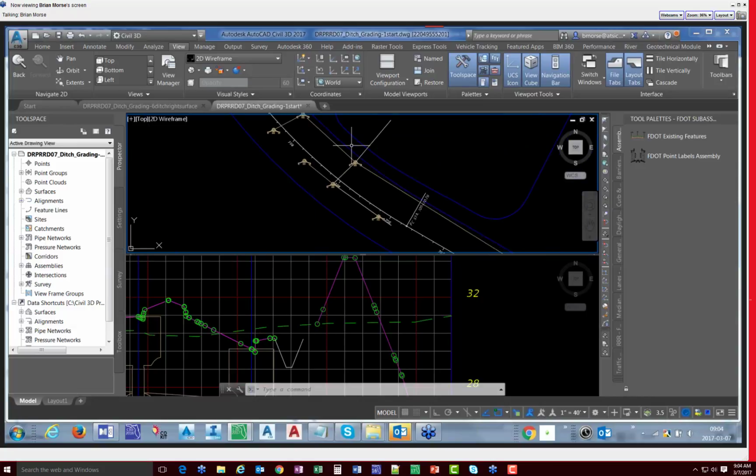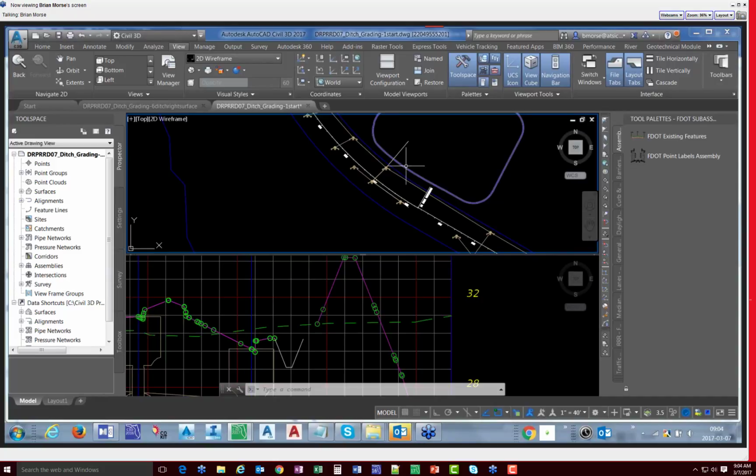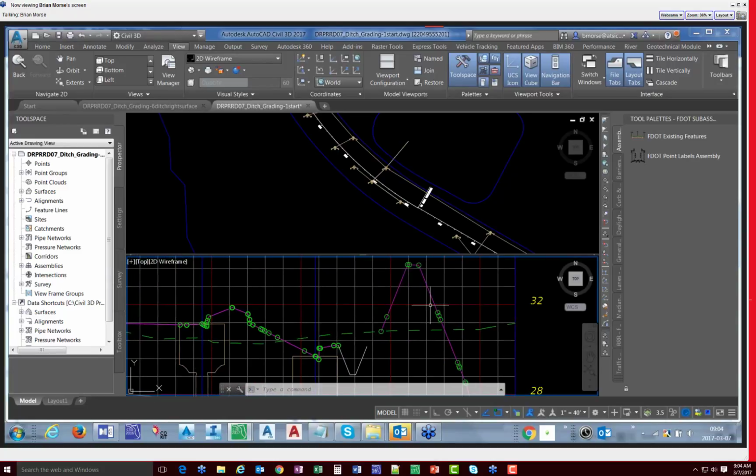What we're going to do is try to fit a drainage ditch right in between the pond and the road, because the berm coming off of the pond pushes the water right into the street, so there's no grading. You can take a look at the profile that we have here. There's the berm for the pond, and this is the back of curb, and then here's our drainage structure. This is the pavement. Of course the two surfaces aren't really connected, but if you did a straight line connection between there, then you'd just be dumping water into the street. We don't want to do that.